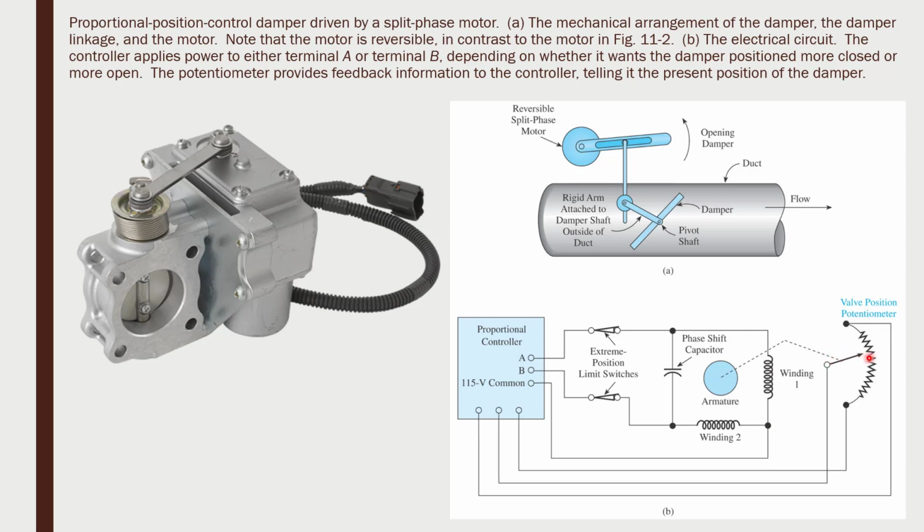And in this particular case, not only am I driving the motor back and forth, because this is a proportional control, not on off. So I can actually vary. I don't have to go from 0 to 100%. I can vary anywhere in between these. This is telling me where I am. This is telling me where that valve is. So if I have an error of 5 degrees and that corresponds to a 20% opening, then this will move, and I'll know when I'm at 20% because the error will reduce.